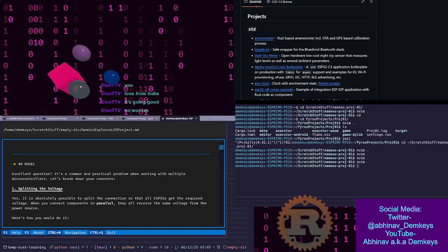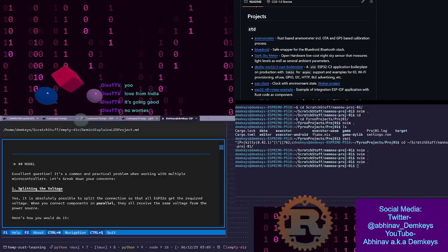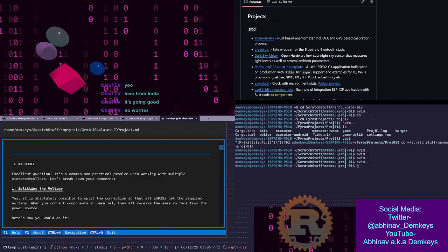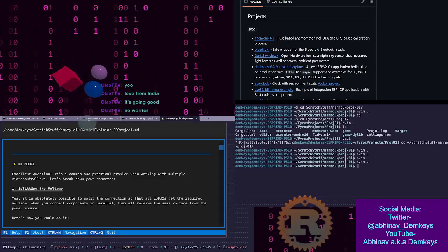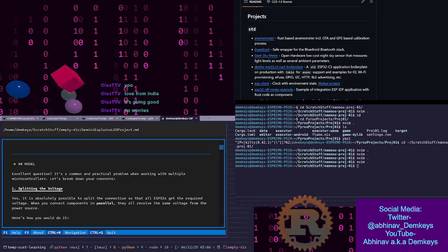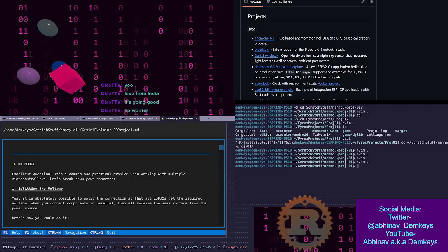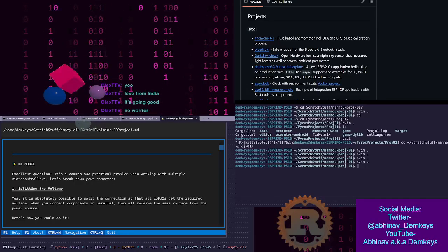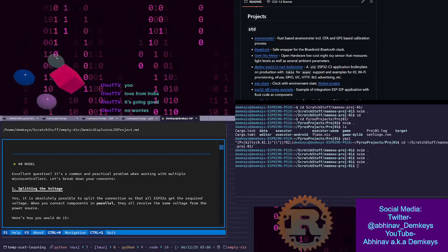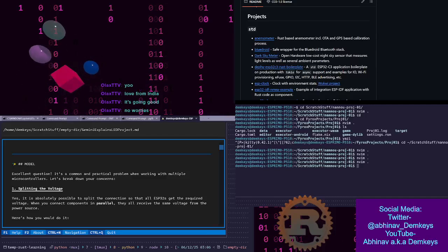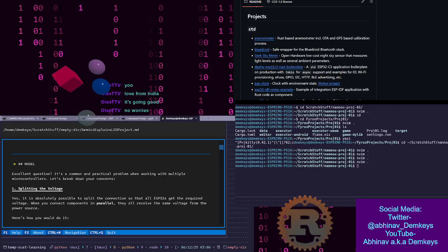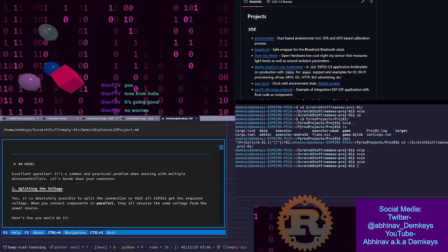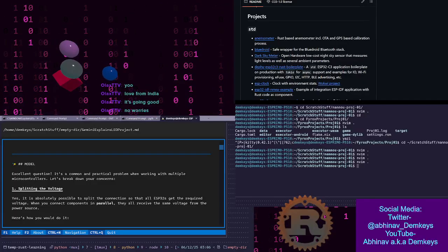And if you're not doing something heavy on the ESP32, you should be fine. If you're just powering LEDs, they take like 20 milliamps usually. So if you've got like 10 of them, you're going to hit 100 milliamps. That's 0.1 amp. So you still haven't touched the limit of the phone charger. So you should be fine.